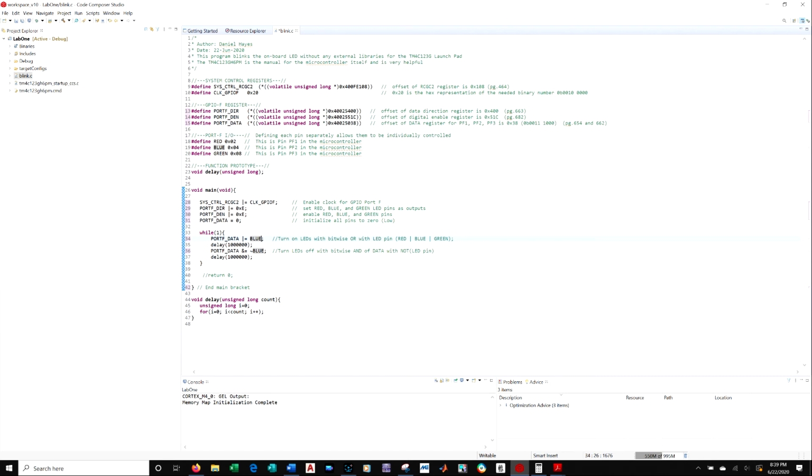So we're not using any kind of special sleep, or I guess you could call it a sleep, but it's not like a defined function for a delay. It's just a software delay. We're just looping, doing nothing until it completes and comes back. A lot of people don't like doing this in programs because it eats up the CPU processor time, but for this kind of example, it doesn't really matter.